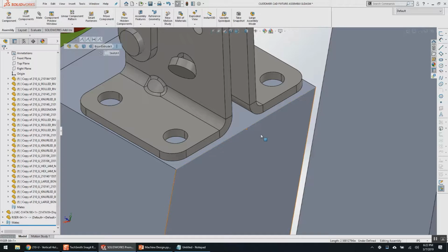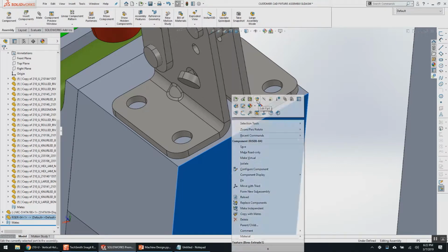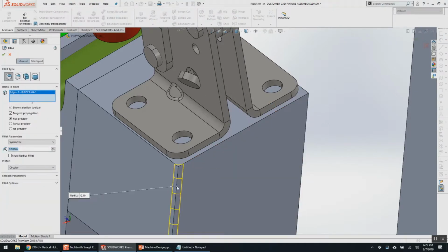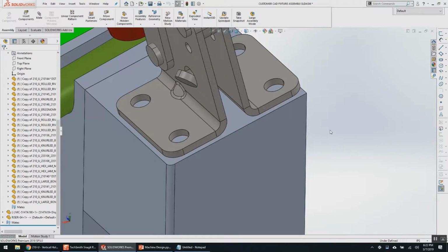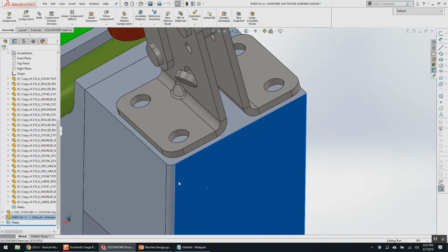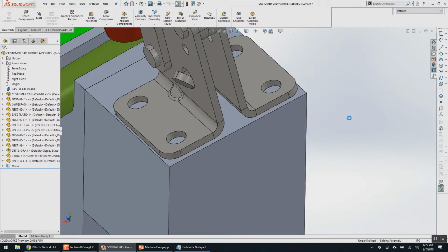The reason I don't like the midpoints is because then if I have to chamfer a radius or I do anything that destroys that edge, and edges are always defined by where two faces join, so if you affect one face or affect the other face, or affect the edge, or maybe, let's say, for example, if this part is edited, and I fillet just this one side, right? Now my midpoint got adjusted. So I consider midpoints to be highly volatile from a design intent standpoint, and from a practical purpose standpoint, I always try to stay away from volatile when possible, right?